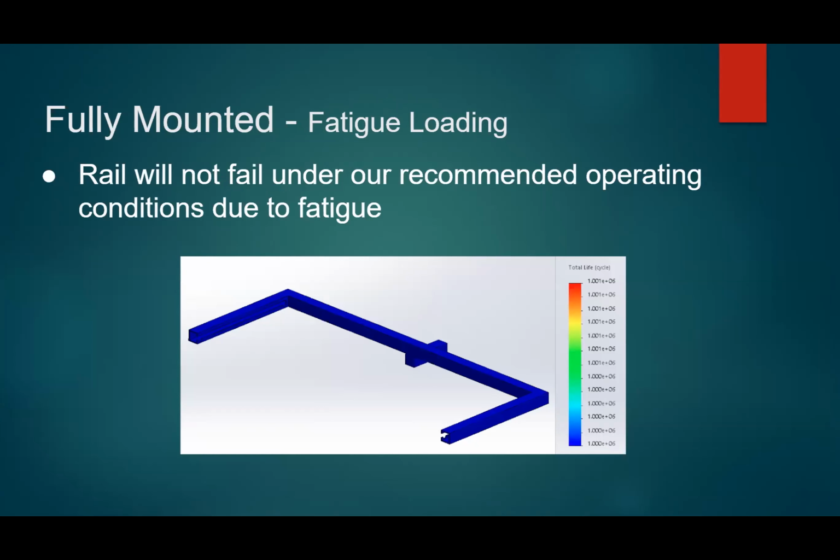Next slide. When you're driving down the road, the enclosure will be in that fully mounted position. So we also did a fatigue analysis to make sure that over multiple applications of the force the rail would still not fail. We did yet another SolidWorks simulation, and this shows that it's rated for 1 million cycles. According to most of our statics textbooks, once you're rated for 1 million cycles, they call that infinite life, which means the loading scenario is not enough for us to worry about any failure due to fatigue.